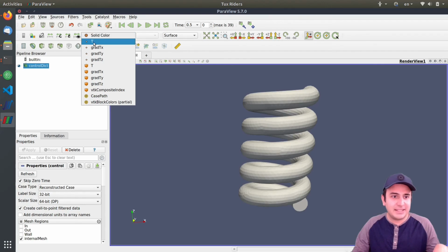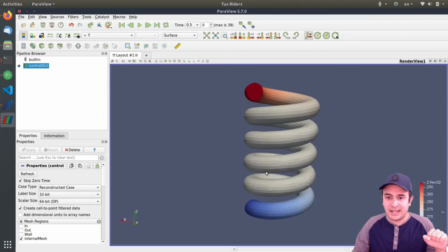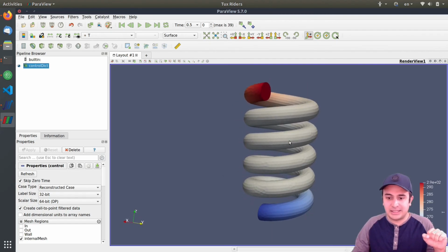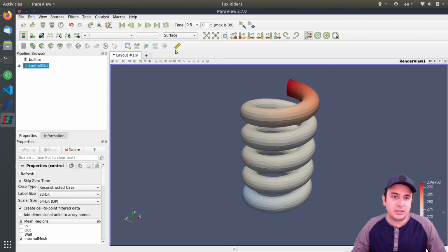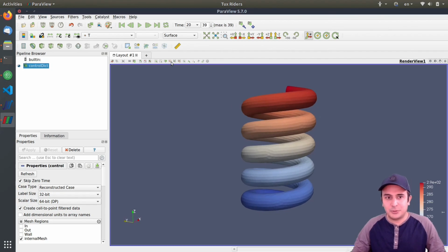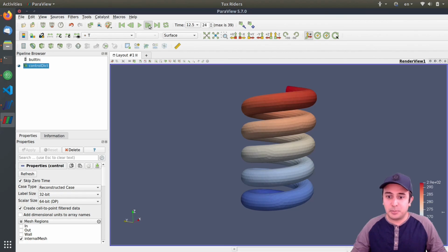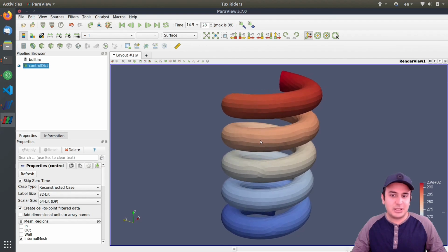As you can see, we have T here in two different formats, both element-wise and node-wise. So I open the node-wise one, and this is the first time step. But you know that the reason it has a fast diffusion is because we chose a very big diffusion coefficient. I press run, and wow, you see how nicely the different temperature fronts, or heat fronts, start to approach each other. So this is quite nice, the way that we took advantage of OpenFOAM.